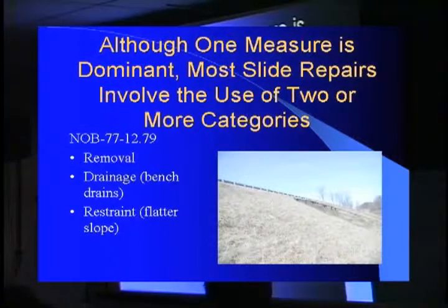Andy, I think, gave an example earlier about a flatter slope not working in that situation. Well, here's a situation where we're going to utilize it, and it's not so much to stop the slide. In that case, I think the slide dipped into the foundation soils. In this case, it's purely in the embankment itself, and the foundation is rock, and so the restraint is more to accommodate the fact that we expect weak soils to be used to fill this back in, just because it's inherent in the area.